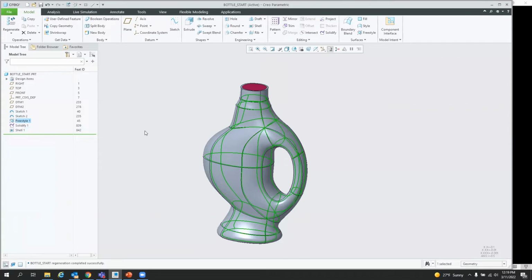So that's what our freestyle surface looked like. If you can imagine doing a lot of surface modeling, and then you ultimately merge those surfaces together, maybe do a thicken or an offset or solidify, at the end of the day you don't really see the surfaces on the screen, but you know that geometry was made from surfaces. So you can just say, show me a snapshot of what that looks like. And that's what we're seeing in red right now.